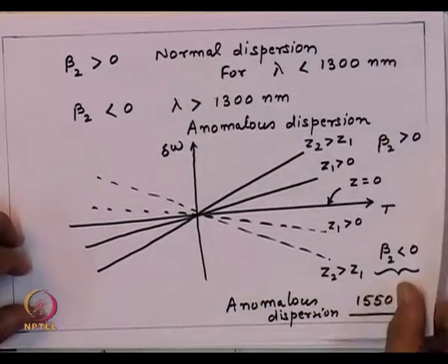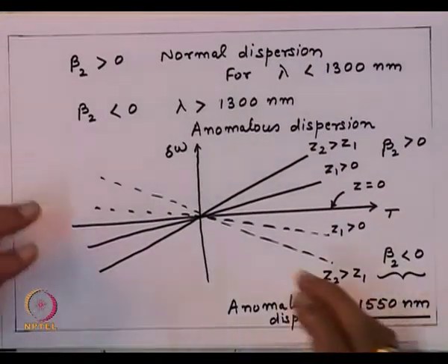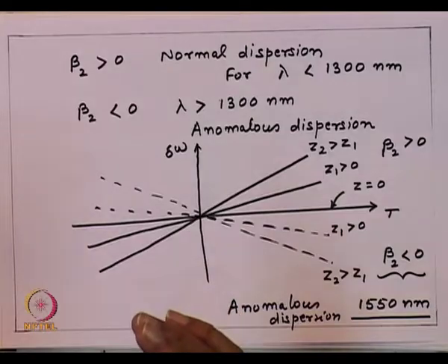So, imagine a situation that suppose now we choose the parameters of a pulse such that the dispersion and nonlinearity both play a role, and they play a role in such a way that the frequency chirp which is created by the dispersion in anomalous regime, which is negative, that negative slope is now balanced by the positive slope created by the self phase modulation.